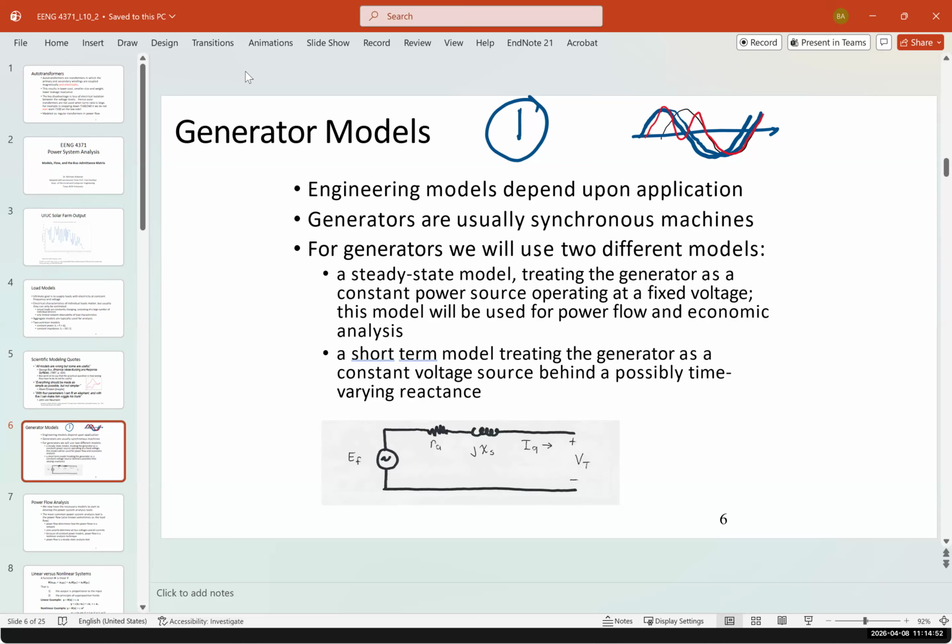First thing, the voltage must match. You can't have a mismatch. If the voltage is lower than the grid or the frequency is lower, the generator would actually act like a motor and it will act like a load. So the voltage should be a little bit higher than the grid. Secondly, frequency must match. If you have a mismatch in the frequency between the grid and the generator, again, you're going to have huge problems. And the third thing, you must match the phase angle. The way that we match the phase angle is by playing with the frequency of the generator that we have control of, and then being able to match that. So that's the reason you shut off a power plant.